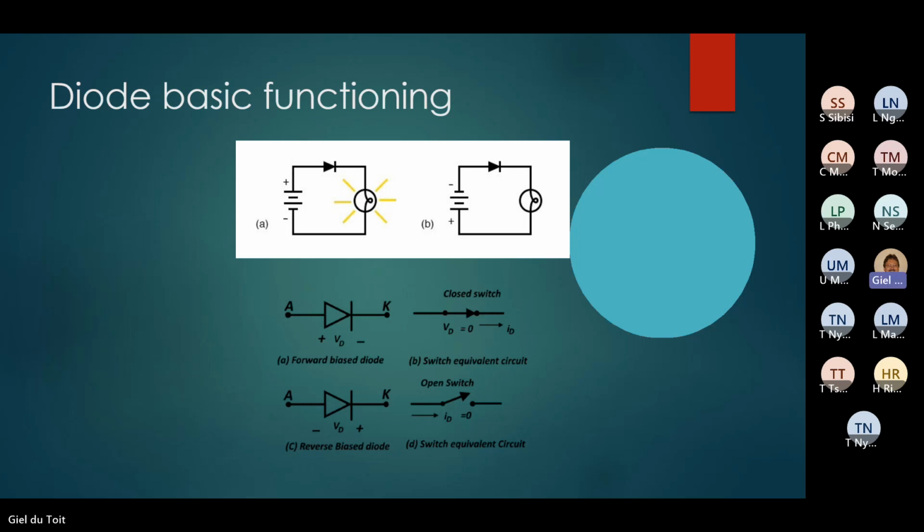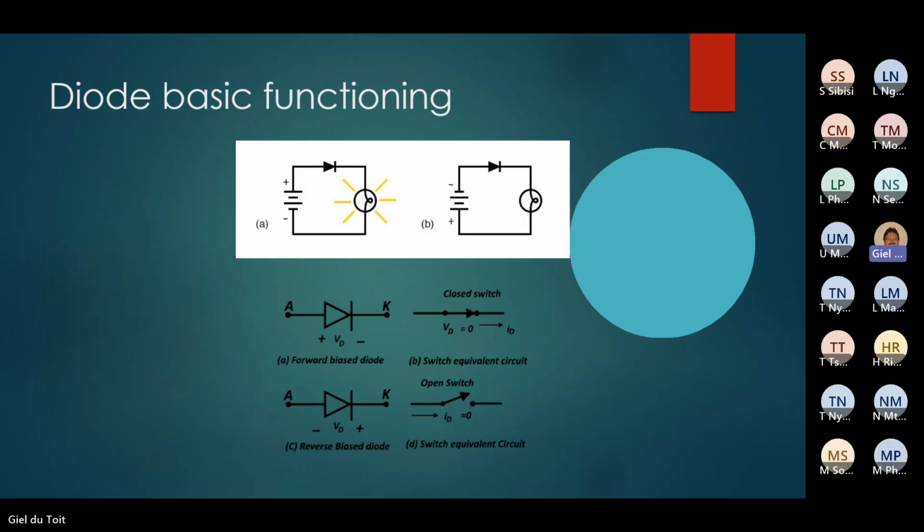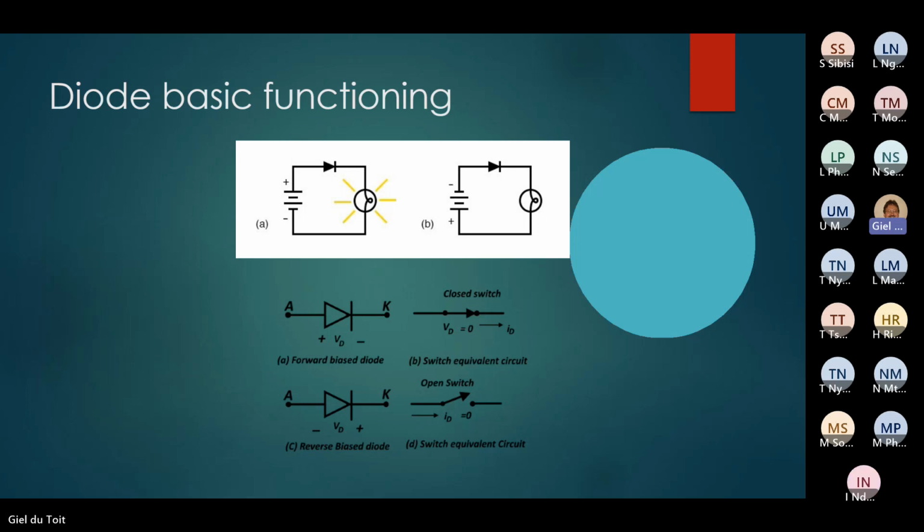So you can see on this diode that the anode is on this side here. It's the plus side of the diode. And the cathode is the minus side of the diode. And I always remember it with this minus here connecting to the little arrow line here. That line is a minus, you see. So that's how we know that's a minus of the power supply. And the plus of the power supply is the anode. So just remember that. All right, so when current flows in this direction through the diode, it is forward biased.